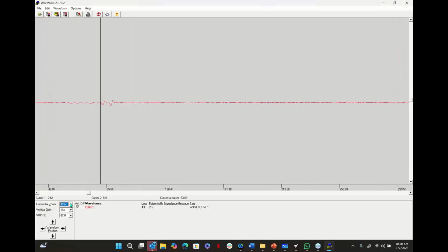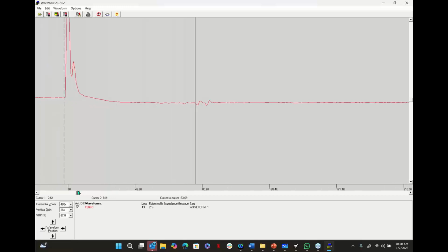As I start to zoom in just a little bit further, this TDR zooms to and from the center of the screen. So I have to sometimes zoom in, move it over, zoom in, move it over. As I start to increase my vertical gain, when I mention what the vertical gain needs to be set at, it's whatever it takes to get something to stand out. I will prove to you that there is a point where it's too much and a point where it's too little, and it's really obvious, and I'll make sure you understand that.